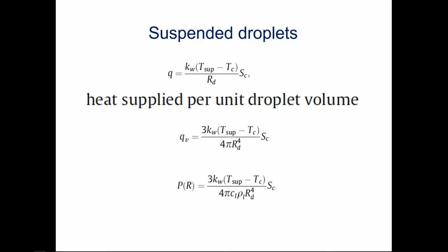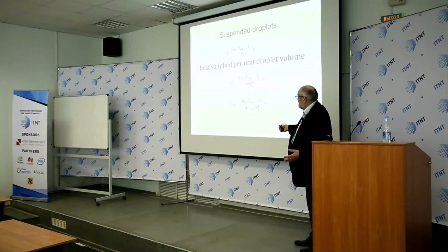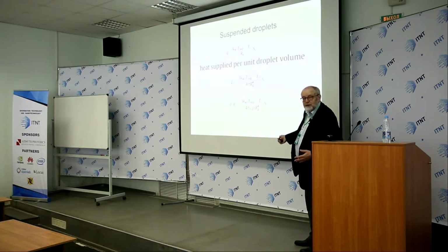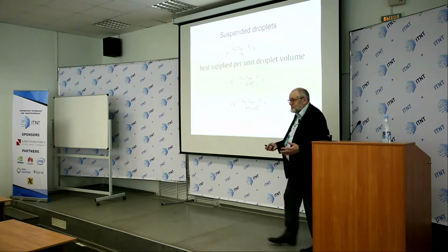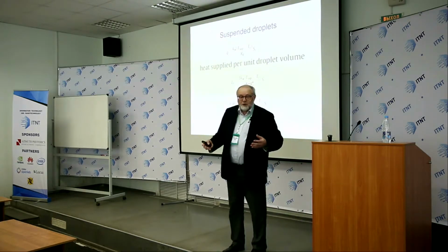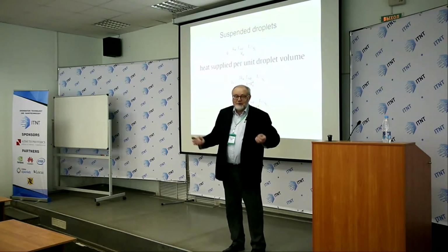And then once we have obtained this heat uniformly distributed inside the droplet, then mathematically this heat can be replaced by this source term in the heat conduction equation. So as you can see, we use the equation which was originally designed to take into account the effect of thermal radiation on heating of droplets, but applied to the case of the droplet which is heated via the rod.